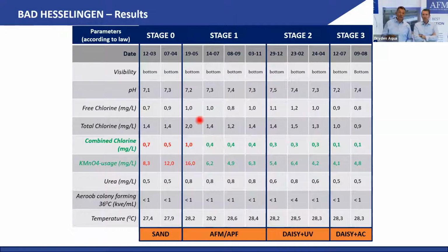And the second learning, if you don't backwash your filter properly, it's like a bin. You get more and more solids in it. You have to empty this bin, and you have to empty it completely. So if you operate it the wrong way, it's not good. If you do it the right way, you're smiling.